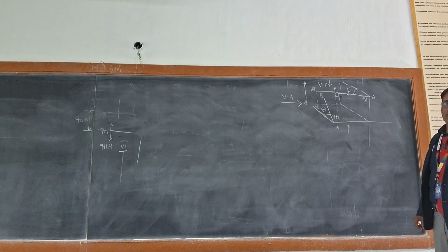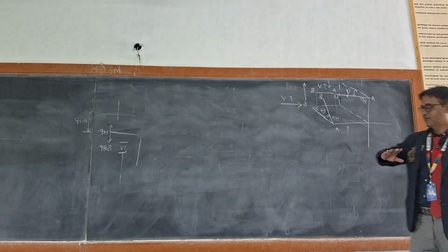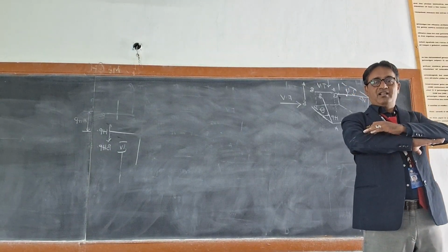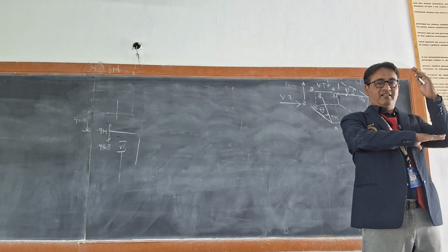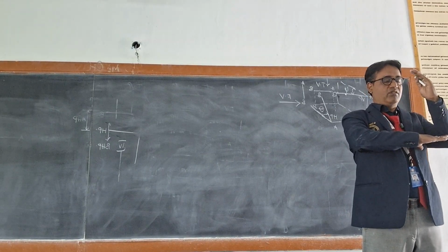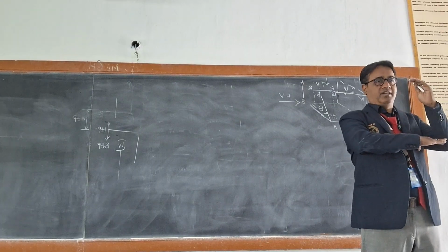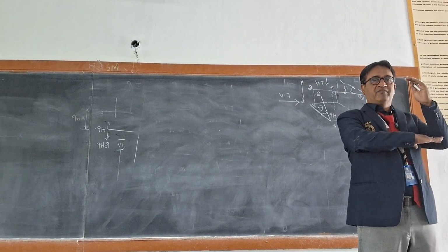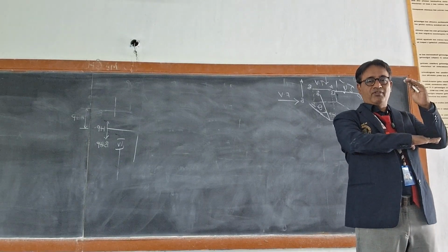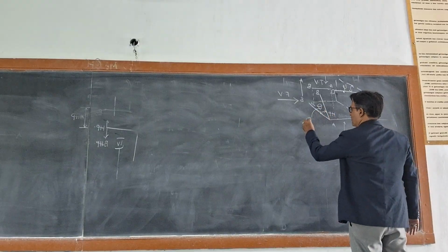So now let us go on to theta and psi. Say, for example, this is my horizontal plane and this is my straight line. Now it is at 0. Now it is making an angle. If you want to view this angle, there is only one possibility: you have to stand in front of the object. Therefore, any inclination to HP can be viewed from the front view. So for this theta, you have to look from the front.